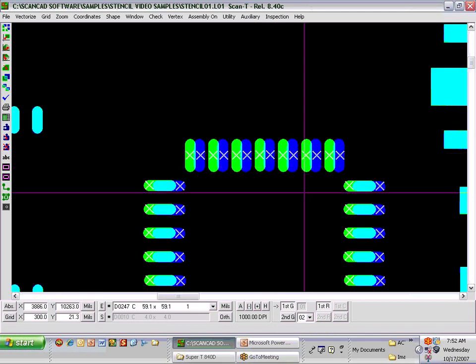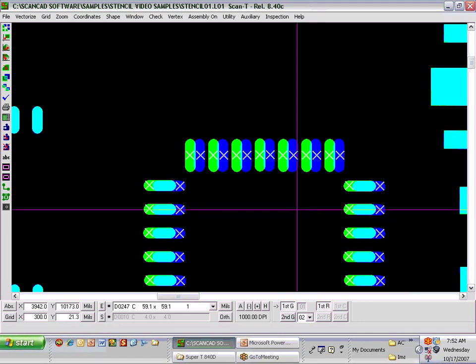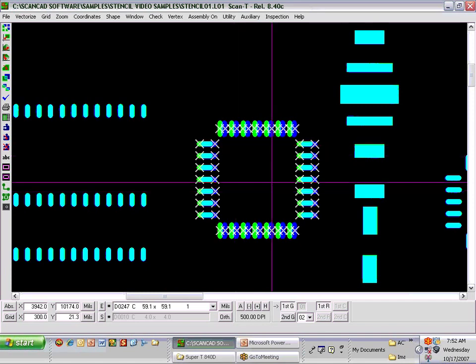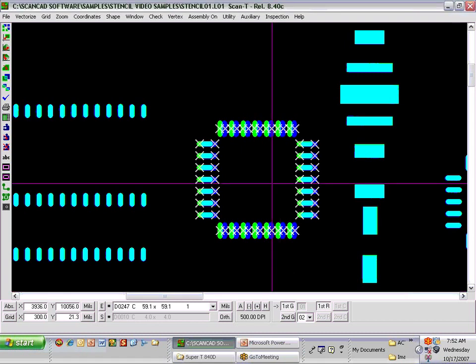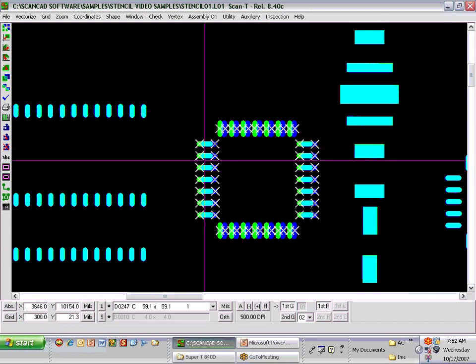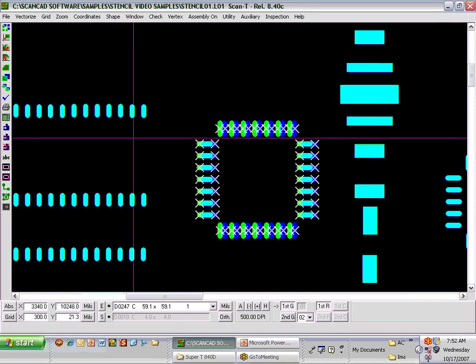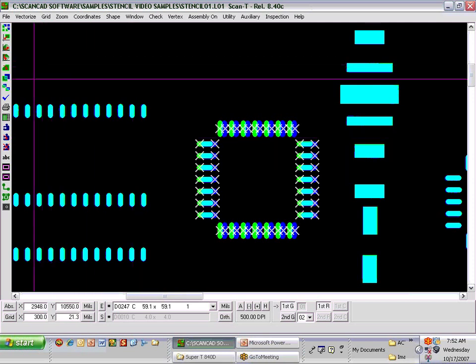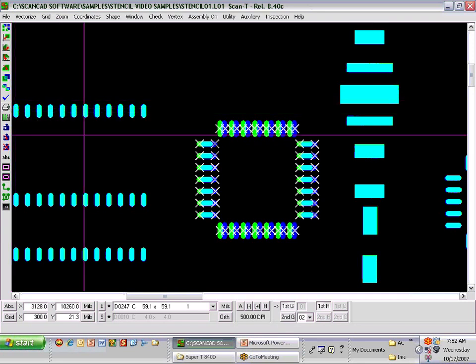And then finally, in this example, for this particular stencil, we show a shifted image. So in this particular situation, this device has actually been shifted to the left, and again, that is certainly not a good thing to have in a stencil. So you can see how easy this system is to work once there is an inspection, and certainly let's assume that it's a good stencil. At that point you would print the conformity certificate, pack it with the stencil, and ship that to a customer. In the case of a stencil user, you could print on the left hand side here, this icon, print the conformity report and indicate that this stencil is ready for manufacturing.